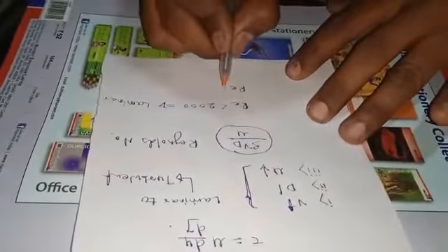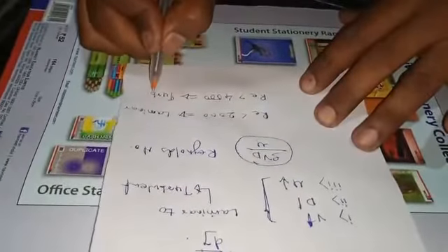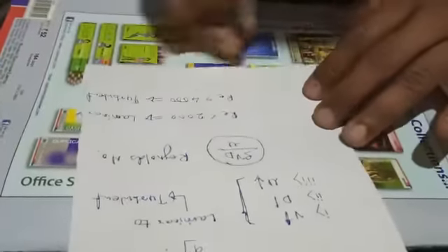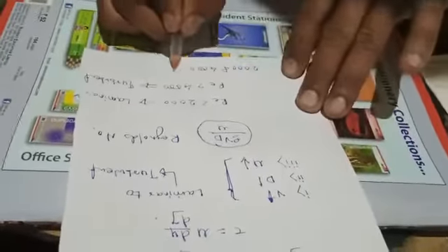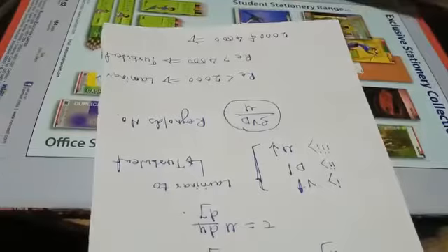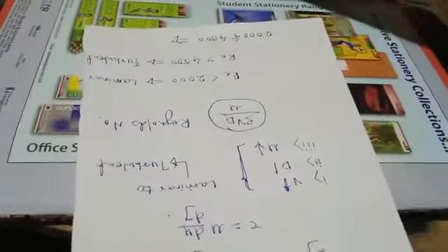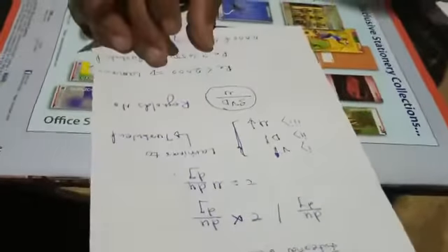If this Reynolds number is less than 2000, then the flow is said to be laminar, and if it is greater than 4000, then the flow is said to be turbulent. If the Reynolds number lies between 2000 and 4000, then we can say the flow changes from laminar to turbulent. Now this chapter deals with the flow of fluids which are viscous and flowing at very low velocity. The following cases will be considered in this chapter.